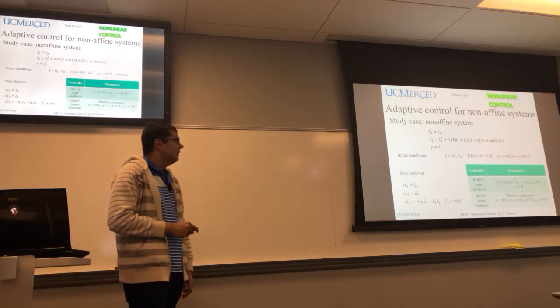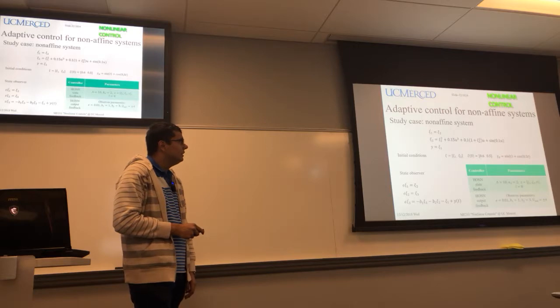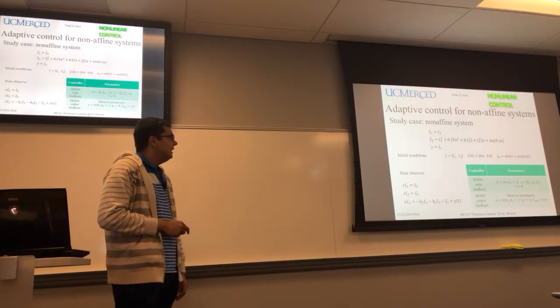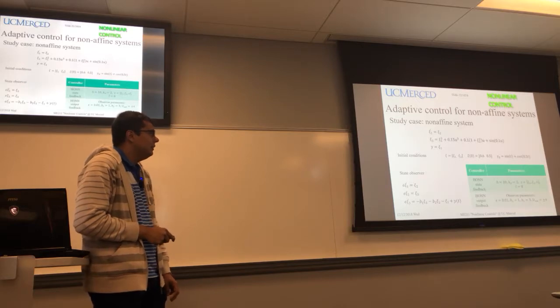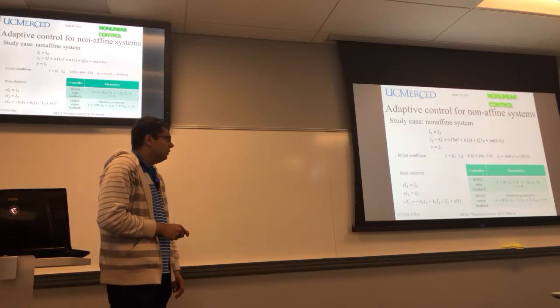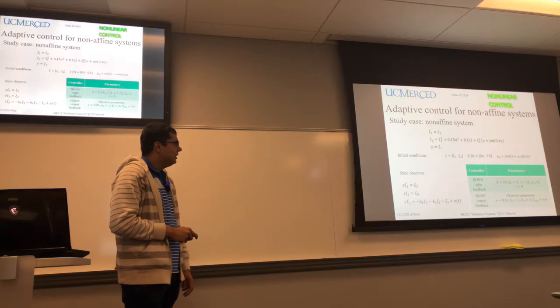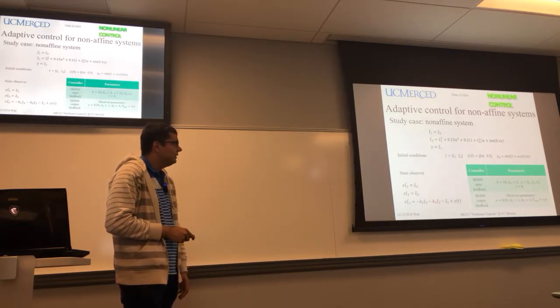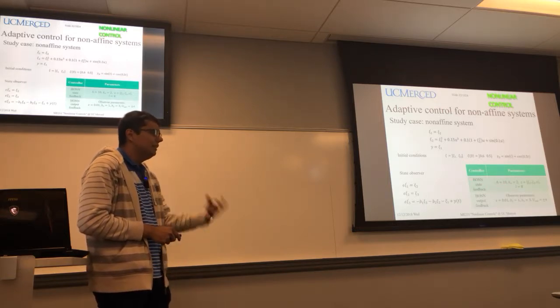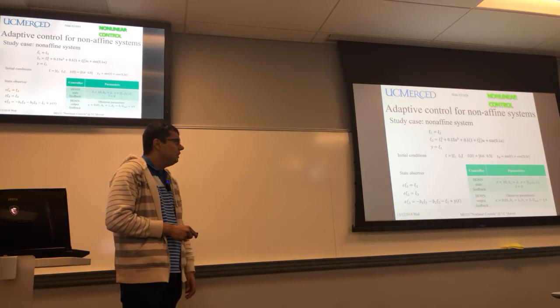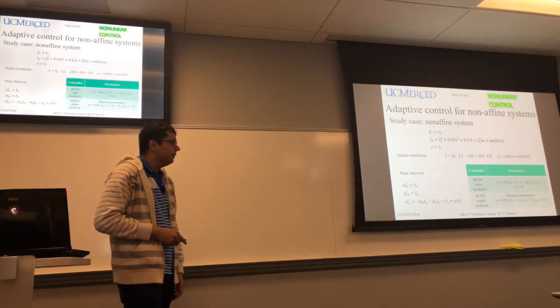So those are the initial conditions for our system. This is our desired tracking trajectory. This is the state of the high-gain state observer. In this case, it's proposed by the authors, has 3 states in order to estimate the chi2 state. Here, we are going to evaluate the performance of the state feedback controller, measuring directly the states, and using the output feedback, in this case with the state observer.